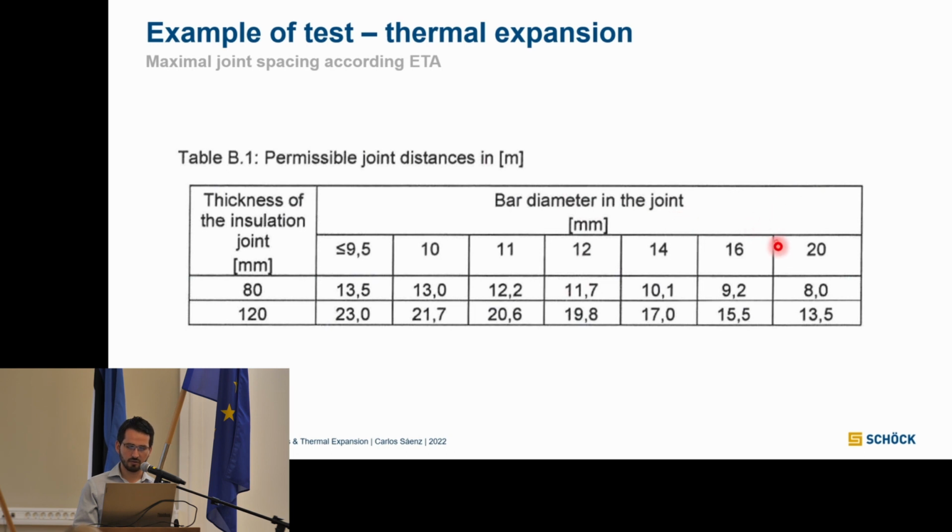So as we said before, because of that relation between force and stress transmitted to our concrete, if we have a lower diameter bar thickness, we get bigger distances for our expansion joints. So this is the design table you get to see: as we increase the length of the balcony, the lower should be the steel element, in accordance to that relation between force, stress, and transmission to the concrete.